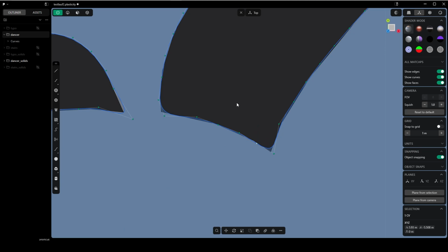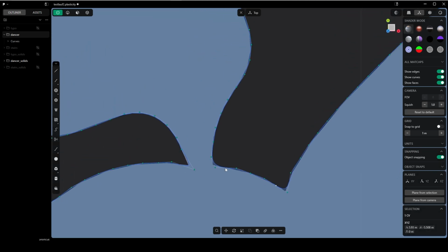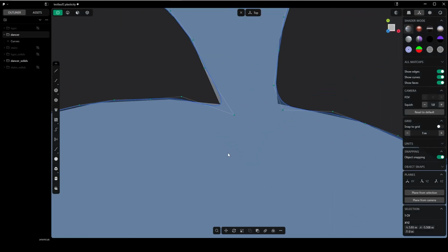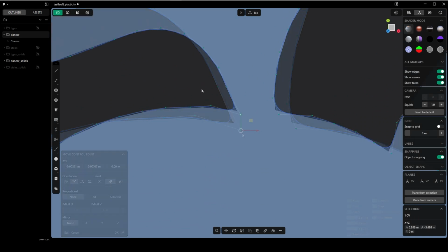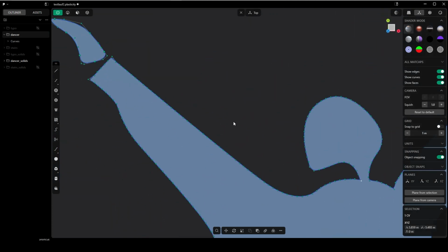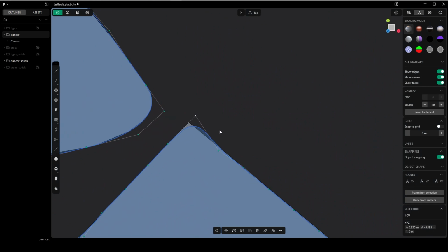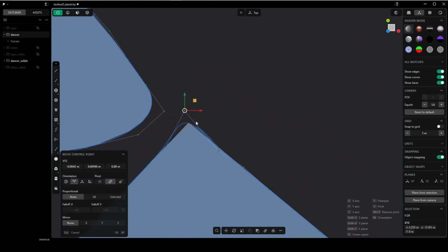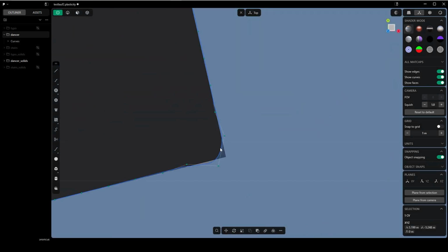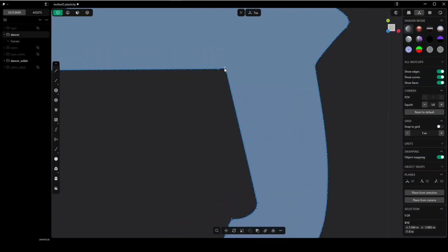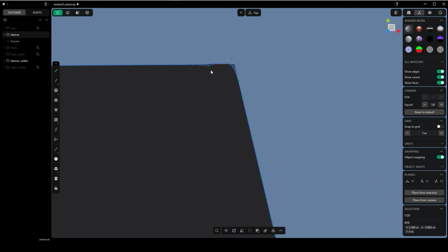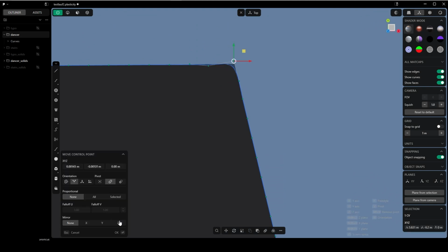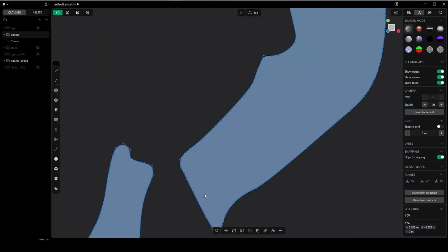There's one thing we always have to keep in mind when we convert 2D shapes into 3D. The 3D world follows much more the laws of the actual world we are living in, and in the real world, there aren't any sharp corners. So that's why filleting or beveling, call it what you want, is crucial. You can't fillet 100% sharp corners like this. It will give you problems. So don't get caught up in that detail. There has to be some rounding.